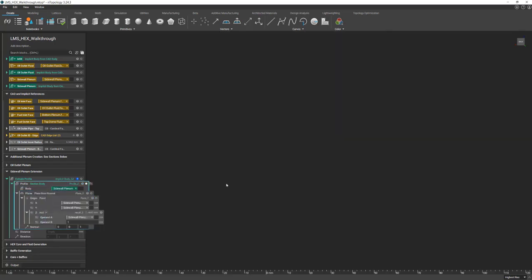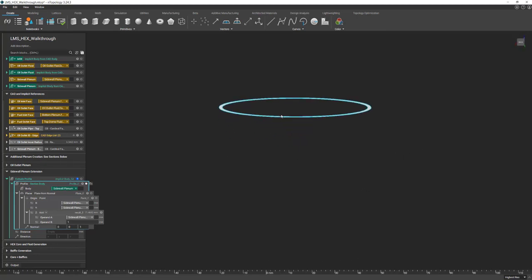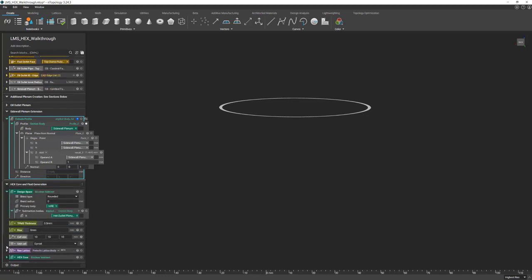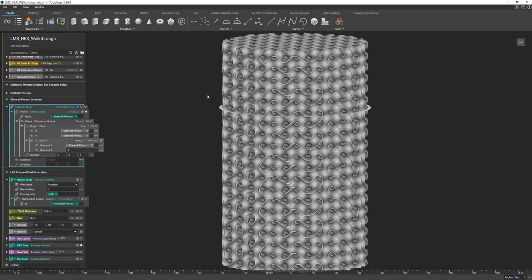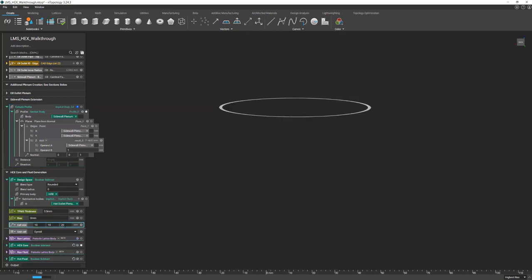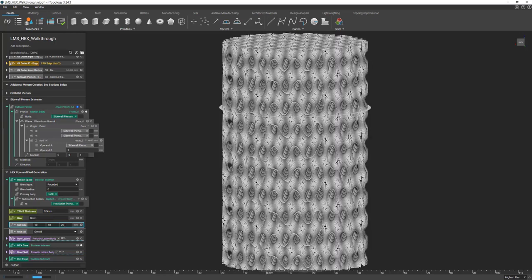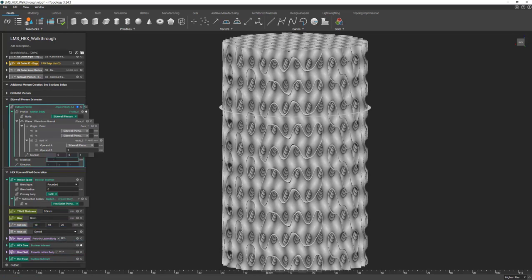So we'll drag this into our section body plane, and we can isolate just this section body and see this is what we're going to ultimately extrude down. I want to tie the extrusion distance to a variable that we've already defined, and in this case I want to tie it to the cell size, and specifically to the cell size in the z-axis. So if I was to change this value to 20, let's say, I want the extrusion to always be covered by the cell size change.